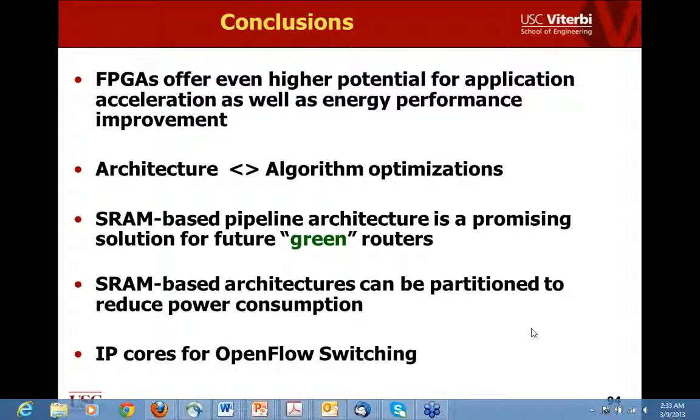I see. So if Xilinx or Altera were to come up with the next generation FPGA, would there be substantial rework in the algorithm, or would it simply flow through? Conceptually, the algorithm does not depend that much on the technology. We said we have a pipeline architecture. We said that controlling the memory power is important. Why? Because most of the power is dissipated in the memory. Unless in the newer technologies the memory power consumption is dramatically so much less that some other factors come into the picture, these ideas will not work at that time. So at this time, the memory is where most of the power is dissipated, and that's where we're attacking the problem.